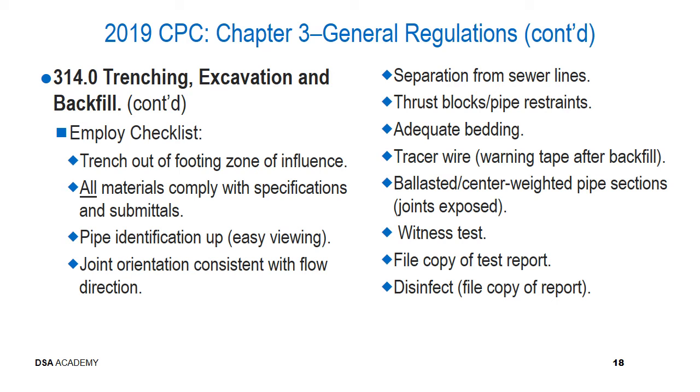You want to make sure that you witness the test. And depending on whether this is fire water, which requires 200 psi for 2 hours, or if it's just domestic water, which requires 1.5 times the normal operating psi for 15 minutes, you want to be sure and witness those tests. You also want to make sure that if the test requires a certain pressure holding for a certain amount of time, you can verify that the pressure on the line is not able to be tampered with and hasn't been tampered with.